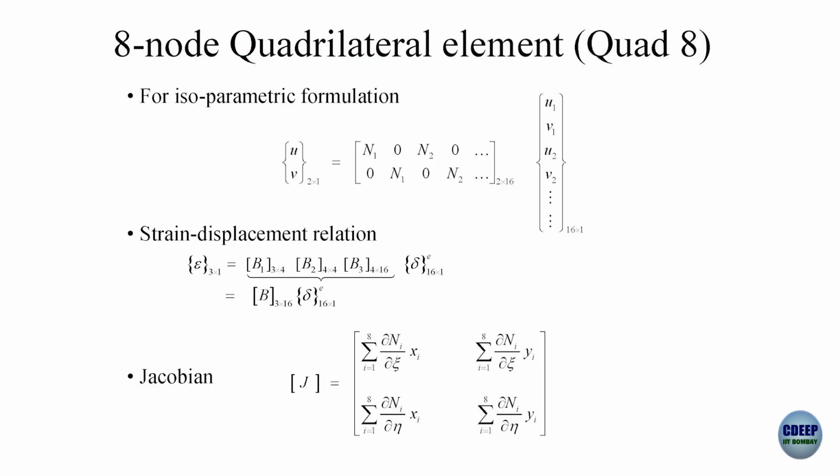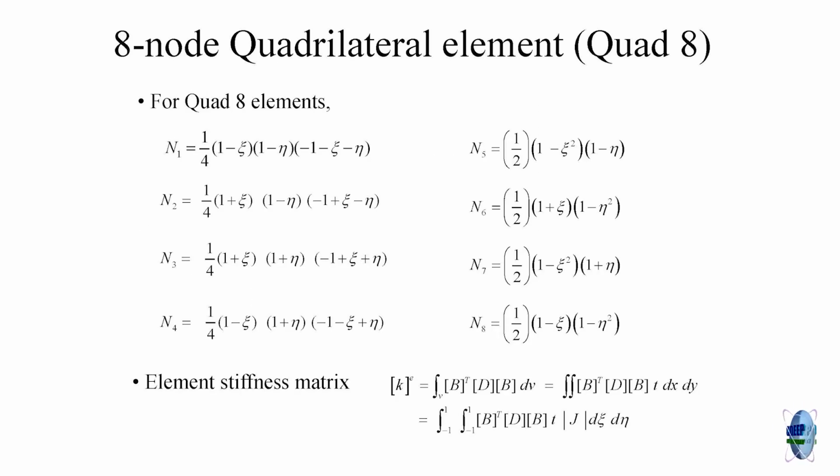Inside that 2 by 2 set of elements, coefficients will be summation from 1 to 8. What are the shape functions, 8 shape functions? I think we have discussed it in one of the previous classes. So, you can take the equation of some lines, product of those things and then derive it, you will get it like this. They are quadratic in zeta and eta.